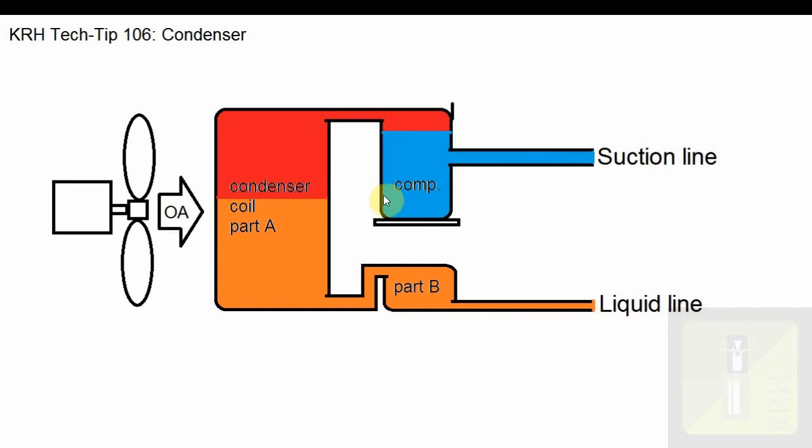As the compressor continues to run, the suction pressure is going to decrease. Refrigerant flow is increasing. We are superheating our refrigerant even more in our compressor, and our head pressure is rising. The red represents the superheated high pressure vapor. The orange represents the desuperheating of that vapor, that we're reaching saturation temperature. Notice we do not have any condensing yet. Though we will be reaching saturation temperature, we have not condensed the refrigerant into a liquid.